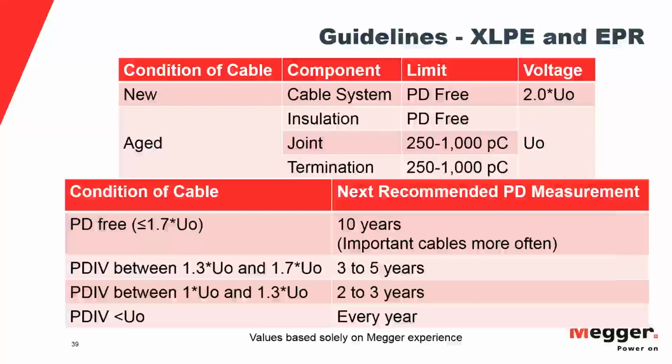The technical reason is inside the equipment there's a fixed inductor. So to get to exactly 60 hertz, you'd have to match the inductor and the capacitance of the cable exactly. And that's not really practical, to have a tunable inductor to match every cable. So we just take an inductor that's suitable for a range, and the frequency then depends on the length of the cable.